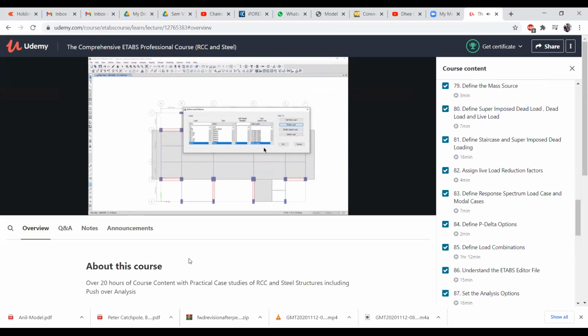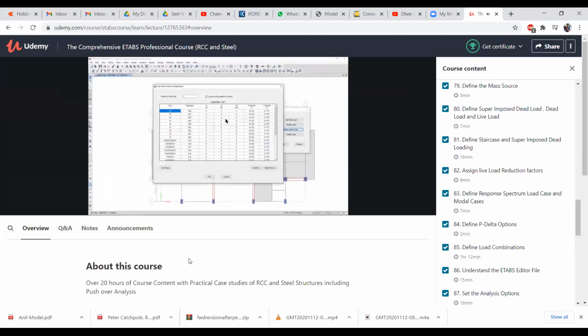When we left click on modify lateral load after selecting this option, you will find that this beautiful table will open. Here it is written X ordinate and Y ordinate. Here it is written Fx, Fy and Mz, and here it is written the diaphragm. So one advantage of using different diaphragms for different floors is that we can apply different loads on different diaphragms.